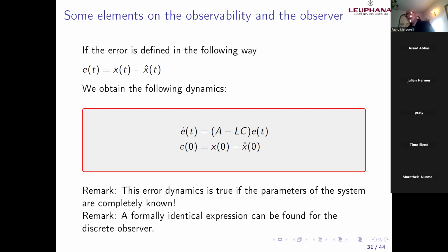I mean, assuming that I can know the system exactly. Do you remember this concept of the parameters? The example which I gave in order to be more concrete is the DC motor. Assuming that I know the inductance of the DC motor, the resistance, everything which physically characterizes the DC motor, the observer which I presented until now is an asymptotical observer. This means I will reach the goal exactly, and I will remain at the goal in infinite time.